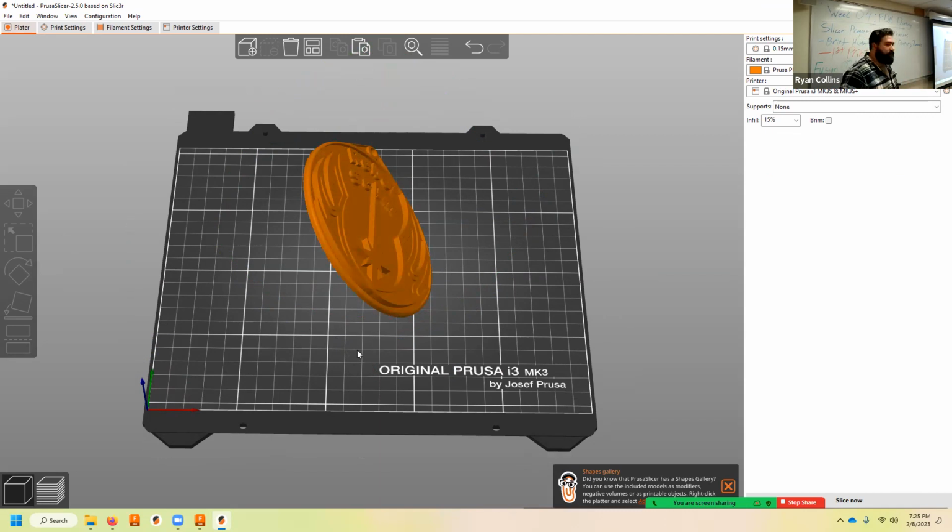It'll be oriented upwards. You can do that manually and try to get it to line up flat, but in filament FDM style printing, you want your object as flat on the bed as possible. And that's why we start with this design, flat smack on the bed.